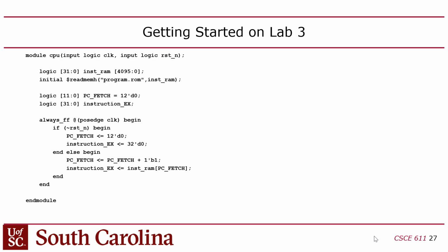be read in here. And then on the FPGA, it'll get included through programming the ROM, which happens when you program the FPGA. And the ROM gets included in the bit stream when you compile your synthesized design. Now, some people say, well, that's a bad way to do it, because that means that anytime you change your program, your RISC-V code, then you have to resynthesize your whole design to get that code into the bit stream, which is then programmed into the FPGA.